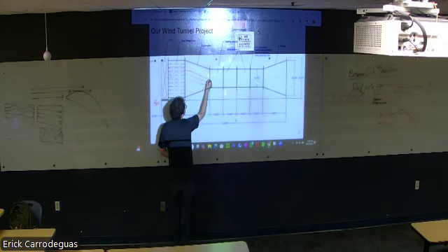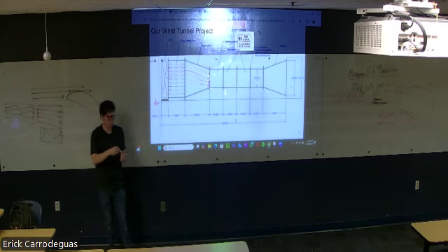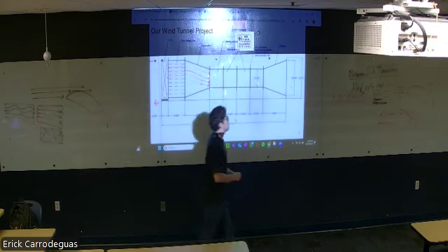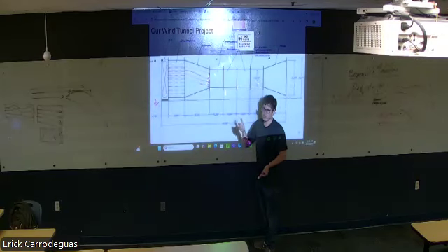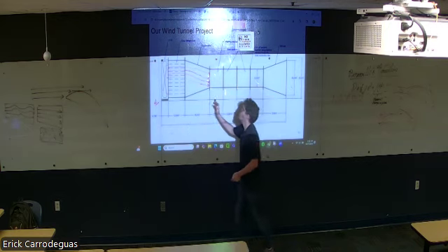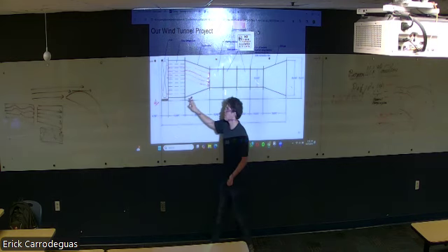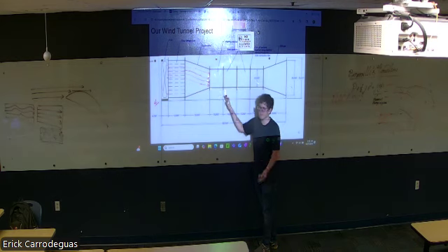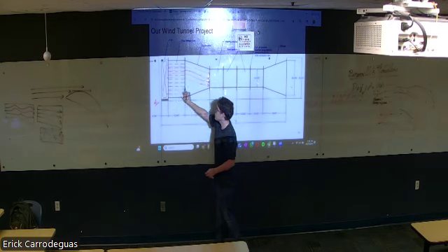And then as it goes down into this contraction, since it's getting smaller, remember Bernoulli's principle. This equation doesn't really describe it well. Think of just a hose. When you press it down, the flow of water becomes a lot faster, right? The same thing happens here: even though this is going maybe 15 miles an hour, once it goes down to this contraction, it could go 30, 45, maybe up to 50, depending on the speed. And once it goes through these flow straighteners, the flow is laminar.